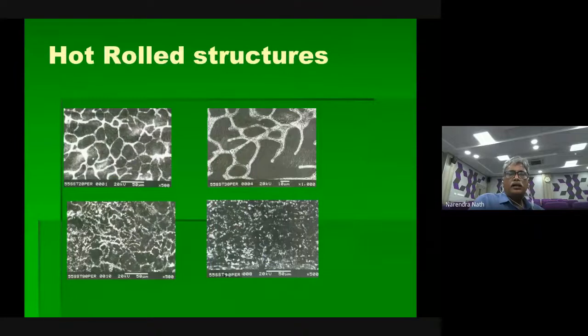And this is again hot roll structures. We tried with different ones, but again, if you zoom in, it looks like our previous sketches, empty pits. You are seeing pits, but actually it is decorated with precipitates.